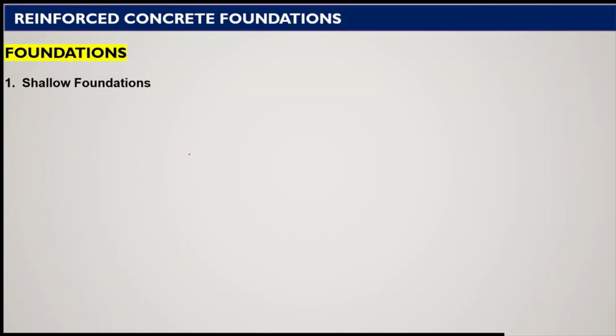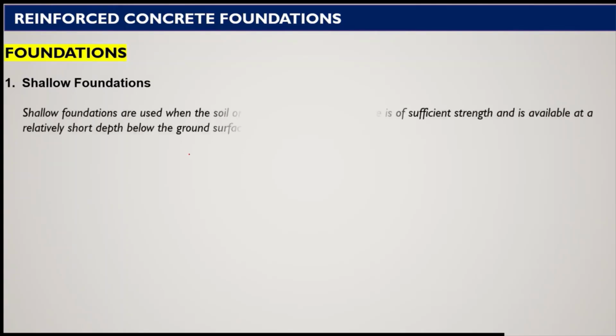So in the design of RCC foundations, let us first of all go through shallow foundation. Now, shallow foundations are generally used when the soil on which foundation is to be placed is of sufficient strength and is available at a relatively short depth below the ground surface.